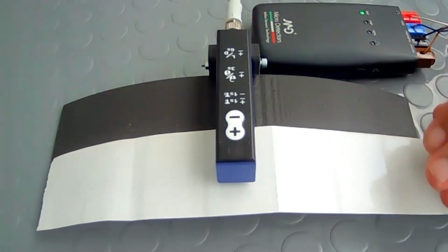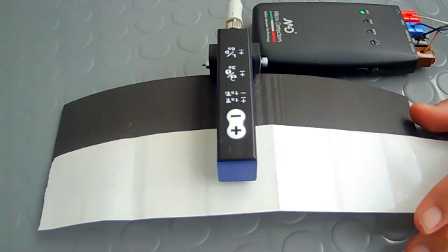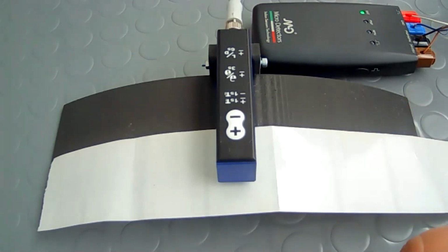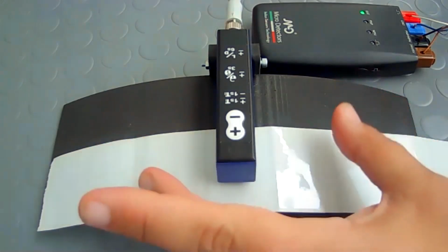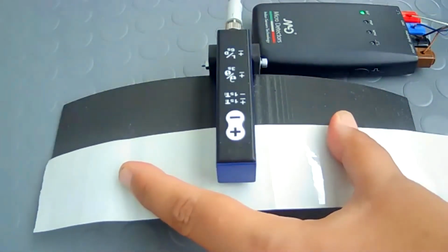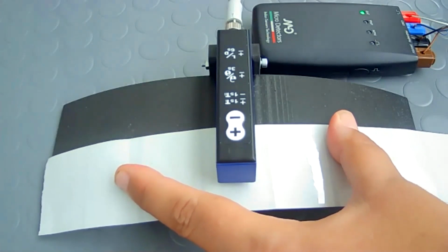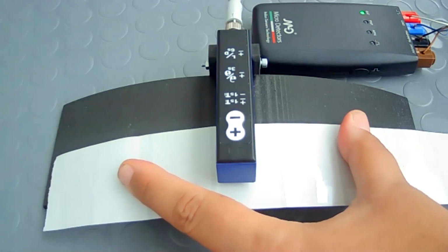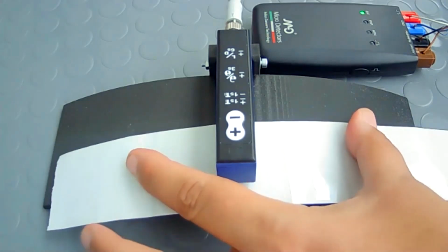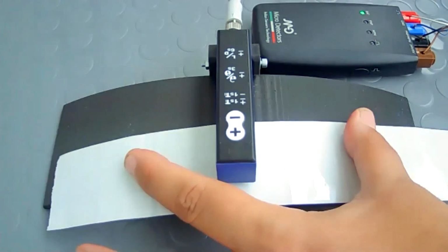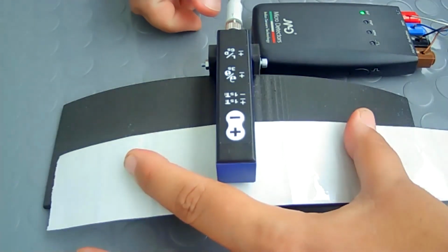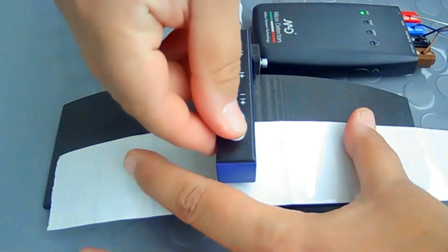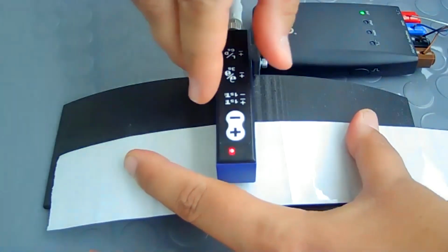As you can observe, Fabrizio is now introducing between the emitter and the receiver of the fork of the slot sensor this labels belt. And you can observe they are transparent. Now we are going to show you how to adjust the sensor through the buttons. How to enter the adjustment mode, simply by pushing together the plus and minus buttons.